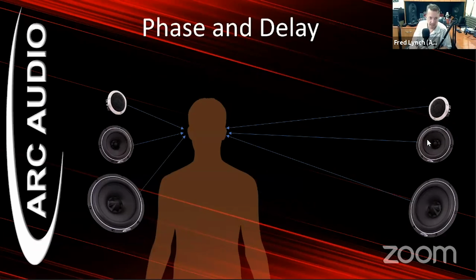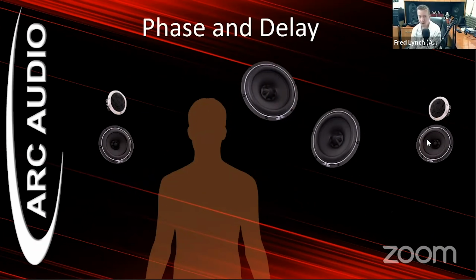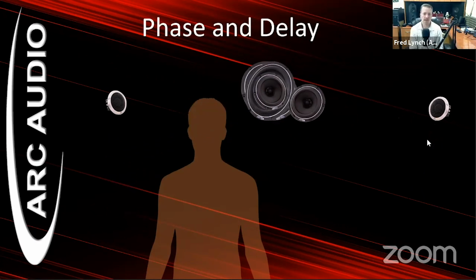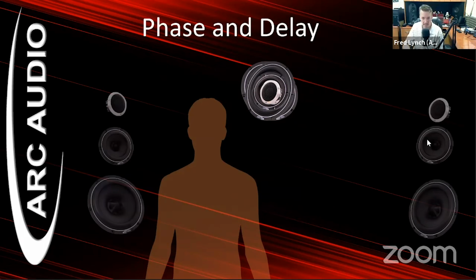Now, phase versus delay. So what we're doing here is we have 6 speakers in this car, and ultimately, if we play a single, full range stereo pink noise phase pulse, we would want everything to sound like it comes from the center of the vehicle in one spot. Not necessarily should we be hearing everything coming from the left or the right side.